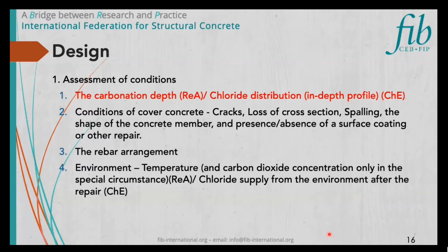In the following few pages, the design of realkalisation and chloride extraction is explained. First of all, the conditions of concrete structures must be investigated. Carbonation depth and chloride distribution are the most important information for realkalisation and chloride extraction, respectively.